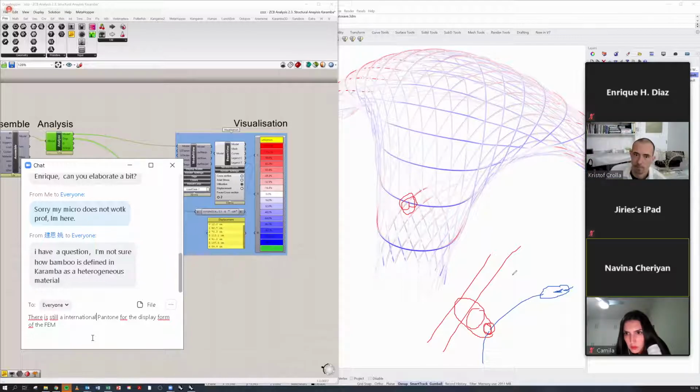And ideally you'll have to give it for all the grids that you've given in this case. You can't really avoid certain grids, and then ideally you should give it for all the diagonals. Say that again. So every square you have, do you have to give it at regular intervals, the diagonals, or can you skip two, three? Well, similar to Frei Otto's structure, he had a diagonal every 10 or every 20 square units. They will become tension lines inside.